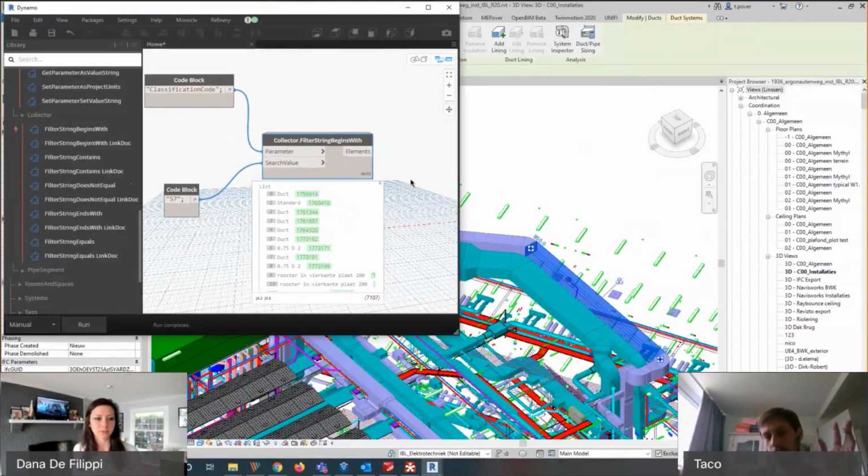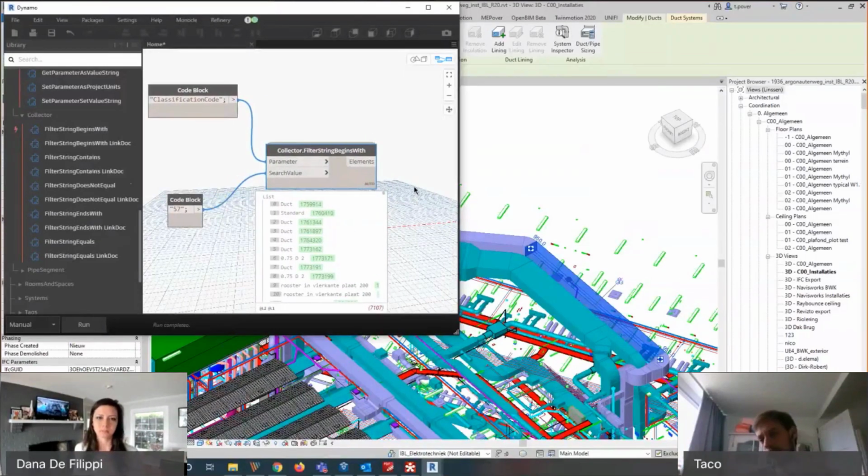What I did was, in the Revit API, you have a few classes, and basically most of it doesn't do everything in the model, but it does everything that is a host object and all its children, which is basically every system family, and family instance and all its children, which is basically every loadable family. So pretty much all bases covered. You got system families and loadable families. Exactly. Unless you get some really weird category, maybe in-place stuff, even masses. Right. Yeah. But for most of the stuff that you want to find, it works really, really fast.